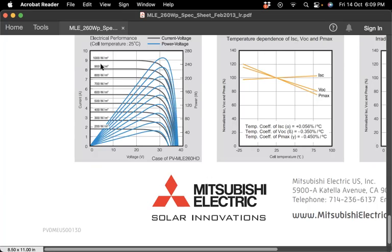This is very normal. The 1000 watt per meter square is the average maximum, not the maximum. So in Egypt, for example, when you do some measurements at midday in June or July, or maybe in August as well, you will find irradiance reaching 1100, 1200, and so on. So in this case, you could expect higher current than usual. And this high intensity, I will consider it in a few seconds, but let's focus here. So this is very normal.